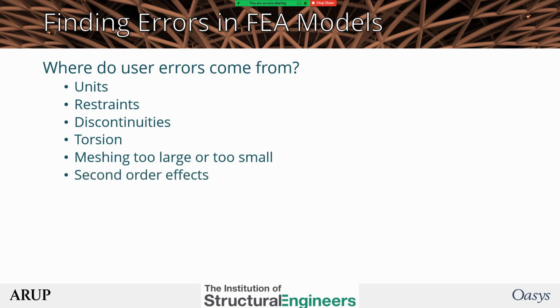Second order effects. If you've got large deflections, you need a non-linear analysis. And then you've got to remember, you cannot multiply or combine results from non-linear analyses. And there's also whatever else it is that you've forgotten.